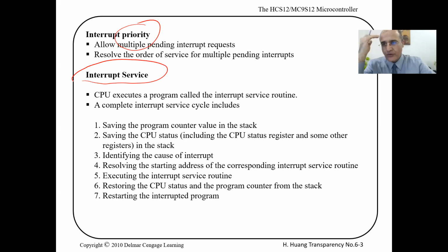So that's why an interrupt will cause the hardware to do some stuff before doing the service routine, so as not to ruin everything else on the controller. We didn't worry about that when we dealt with branching instructions or subroutines, because we know when a subroutine is going to come, and all we cared about was to save the return address in the stack. But here you don't know.